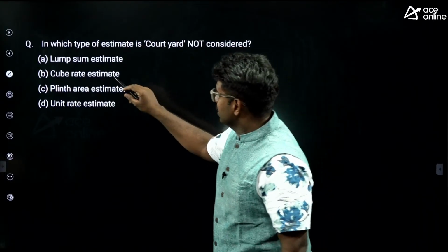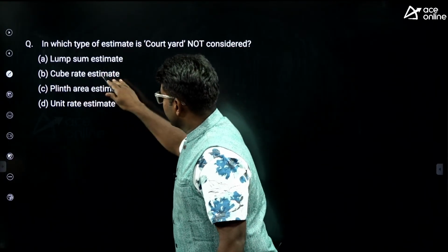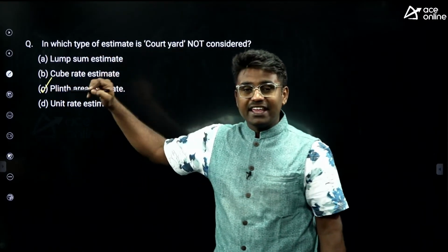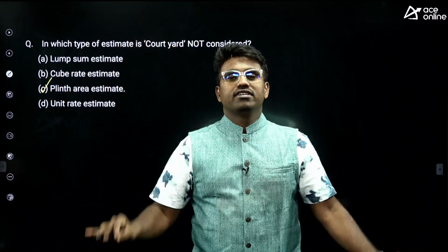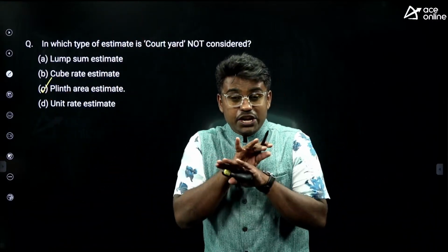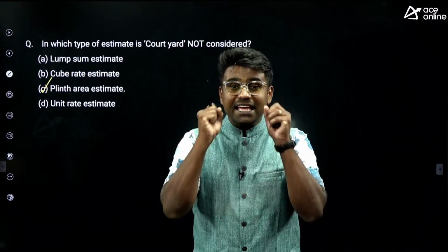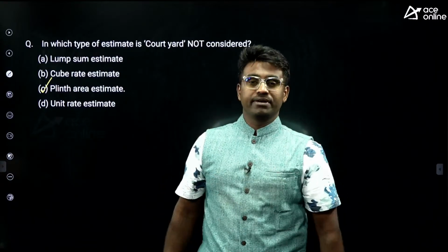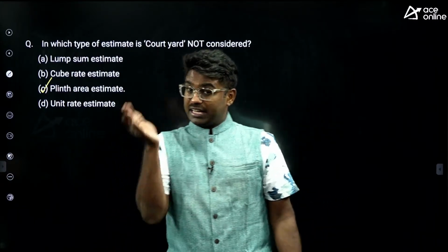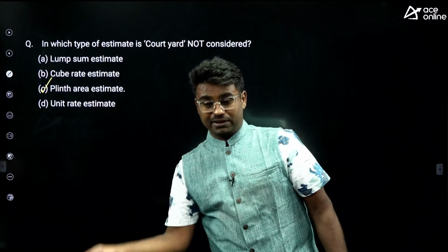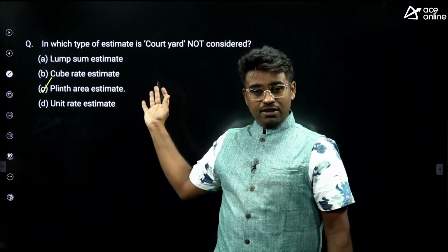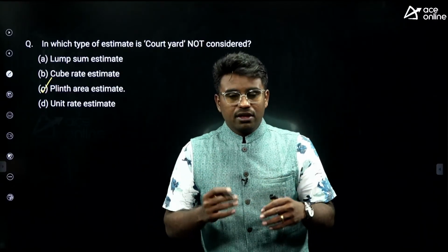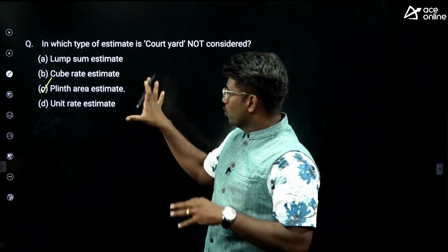Lump sum estimate, cubic rate, which one? Plinth area estimate. In plinth area estimate, courtyard is not considered. It is not considered in the plinth area. That is what you have to remember. Right? Plinth area, what is included, what is excluded. We have discussed these topics. If you have gone through the series on the online platform, then you have a perfect answer for this.